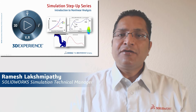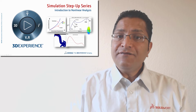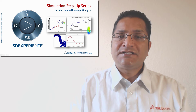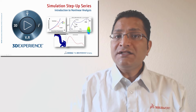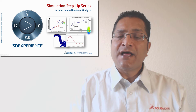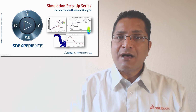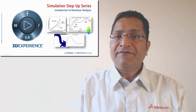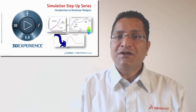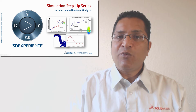This episode is an introduction to nonlinear analysis in SOLIDWORKS Simulation. We'll look at the differences between linear and nonlinear systems, see what assumptions are made in linear systems, when they break down, and when it is warranted to actually do a nonlinear analysis. We'll look at the different shades of nonlinearity in structural problems. And finally, we'll take a look at some general guidelines and flowcharts to help you make the decision regarding whether a linear analysis or a nonlinear analysis is the way to go. So let's get started.